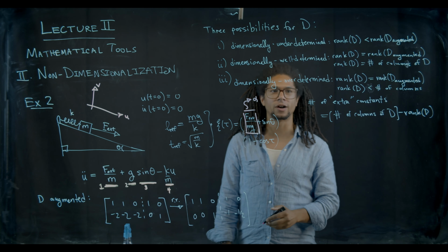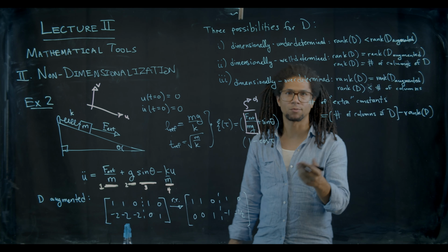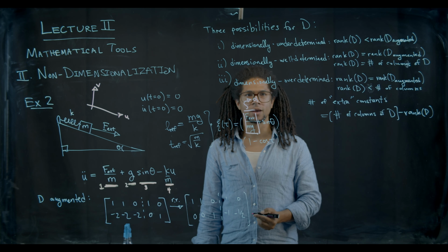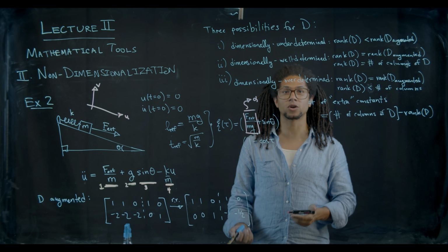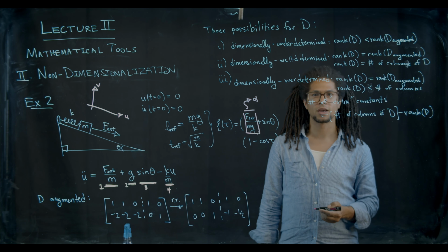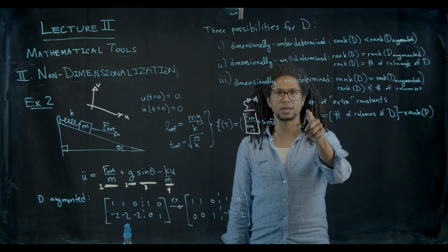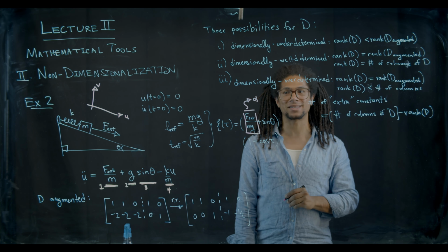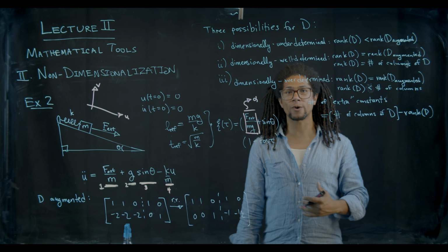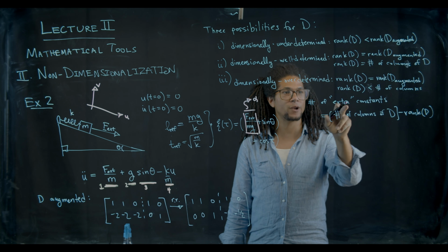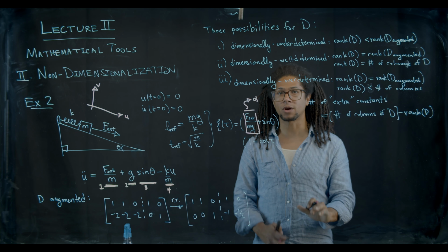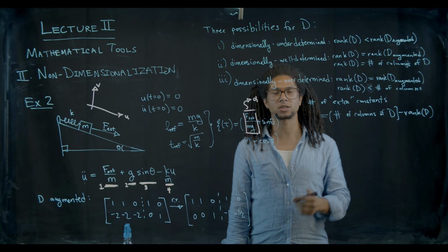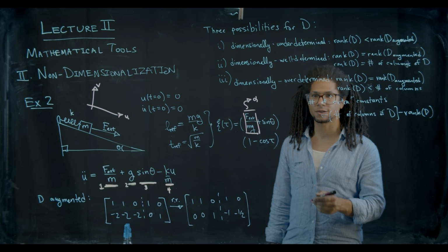This is called alpha. Or I suppose we can call it alpha. And alpha is our first example of what's called a dimensionless parameter or dimensionless constant. Now the number of extra constants is exactly the same as the number of dimensionless parameters, because for every extra constant, we can divide by the reference quantities in some combination to come up with a dimensionless parameter or dimensionless constant.